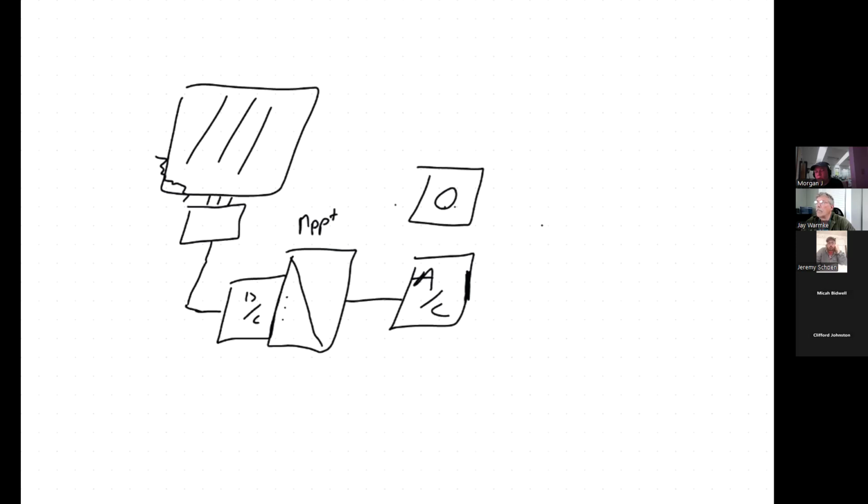Is that a transfer switch? No, it's manually done. They'll just pull your meter. Oh, okay. When you pull that meter out, that meter measures the electricity that's being drawn in and actually going back out. If you ever pulled it out, there are like 4 slots that fit in, and it's acting just like a fuse. When you pull that thing out, you've disconnected the home from the grid.